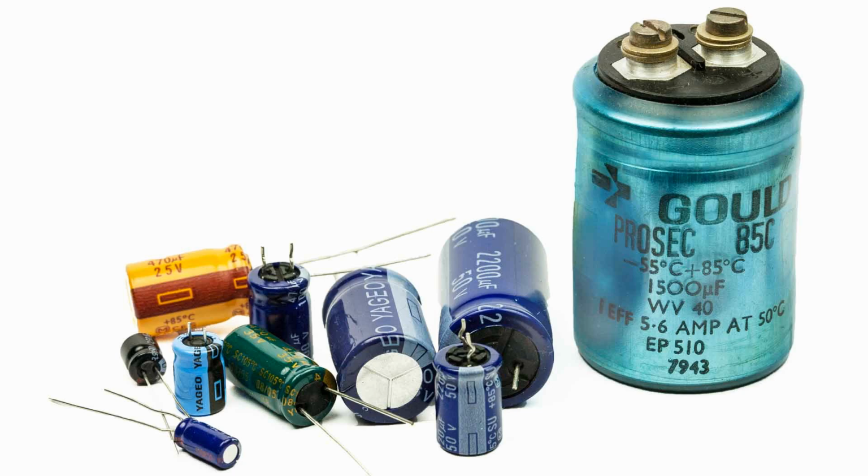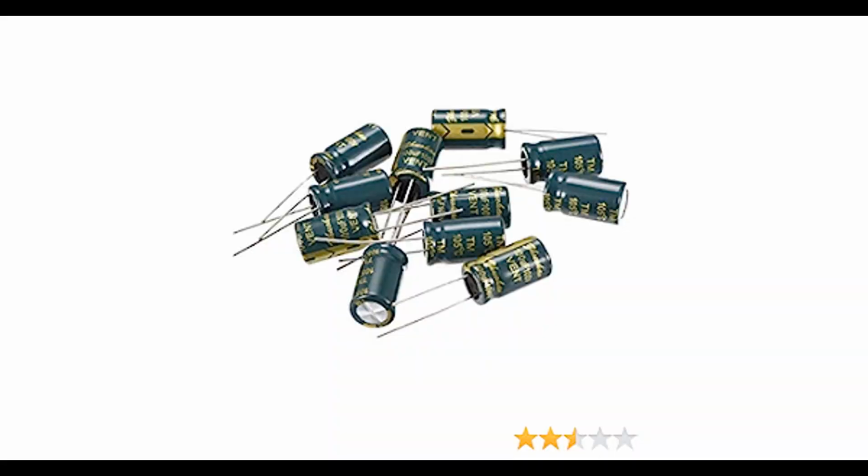ESR, equivalent series resistance. Aluminum electrolytic capacitors. Aluminum capacitors have higher equivalent series resistance, ESR, compared to tantalum capacitors. The ESR of aluminum capacitors can limit their performance in high-frequency applications. Tantalum electrolytic capacitors. Tantalum capacitors typically have lower ESR, making them suitable for applications that require low ESR values, such as high-frequency circuits. Applications. Aluminum electrolytic capacitors.